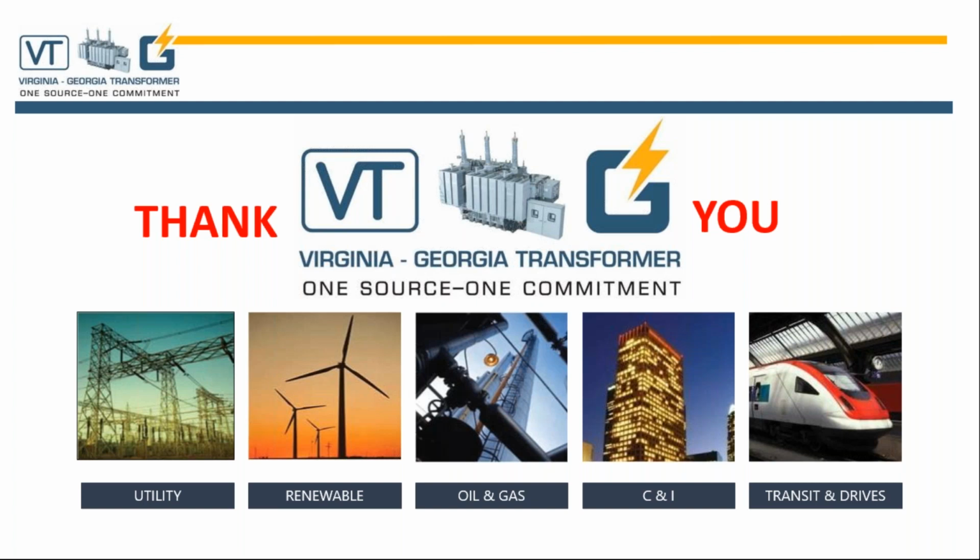Very good. Is there anything that can be done to mitigate these problems on an existing transformer, or is replacement the only good option? I'll take that. Actually, the answer to this question was already discussed in some of the slides before. There are some regulators that can be put in, some digital circuits. Replacement, I don't know if I want to get to that level, but voltage-regulated distribution transformers are an effective measure, as we stated in one of our slides previously. So when you obtain the copy, that is in the conclusions of reverse power, one of the solutions recommended by the experts.